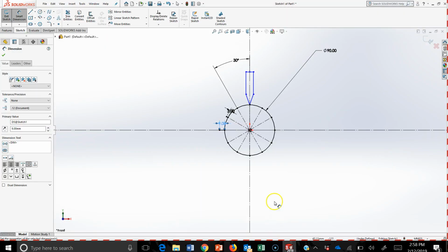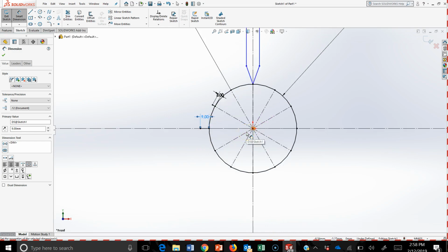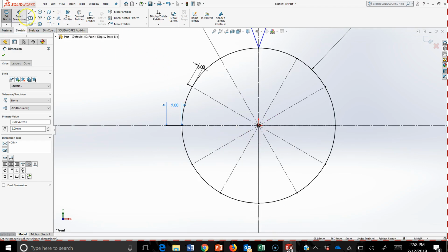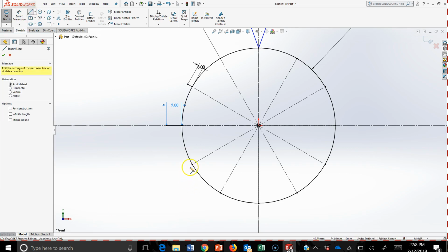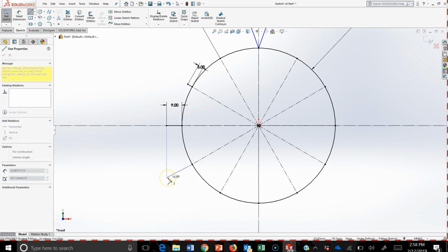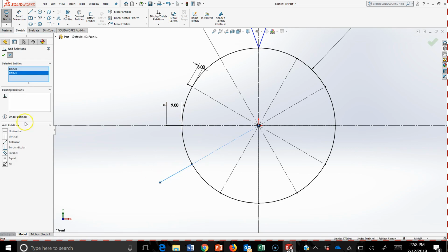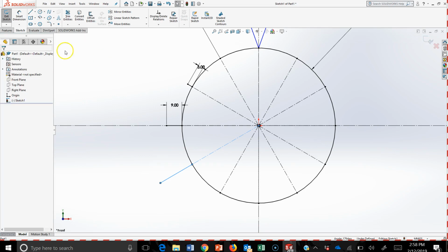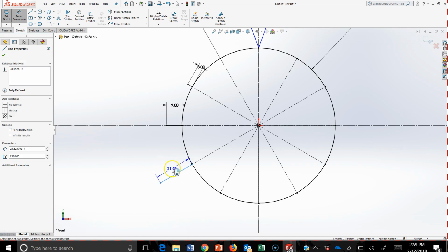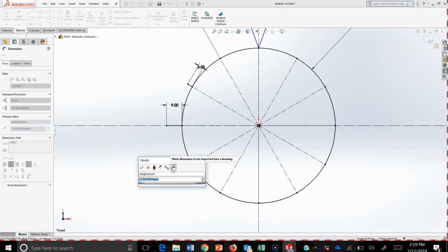All right, back to SolidWorks. So we can see here, I'm just going to scan it a little bit to get a better perspective. Let's go ahead and build another line. And I'm not looking for any constraints there. I'm just going to make sure I add these relations, so when we build the spline, we don't have any troubles making sure that these two lines are collinear. And we'll dimension this. And we're going to do this process all the way through 360. In fact, we can stop at 330 since 360 brings us back to the home position.